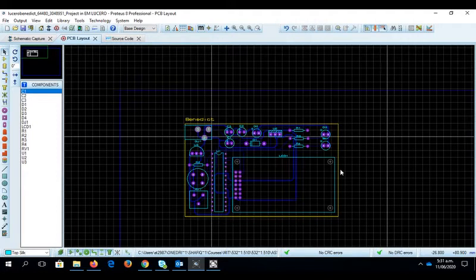That means the technical specification for all the layers can be produced separately, so that the film negative, the PCB negative of each layer, can be generated for production. So this is an important step for PCB manufacturing.